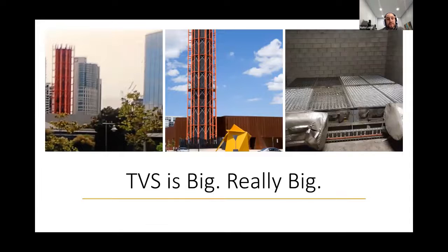Tunnel ventilation systems are really big. Just need to get that out there in terms of when we're talking about infrastructure, flow rates are quite large. If you are working on a building and you have 100 meters cubed per second of smoke exhaust, somebody's probably going to ask you to double check that you're right and that you didn't add a zero somewhere. If you're working on tunnels and you have 100 meters cubed per second, somebody can say, is that only half of it? They're really quite large systems.